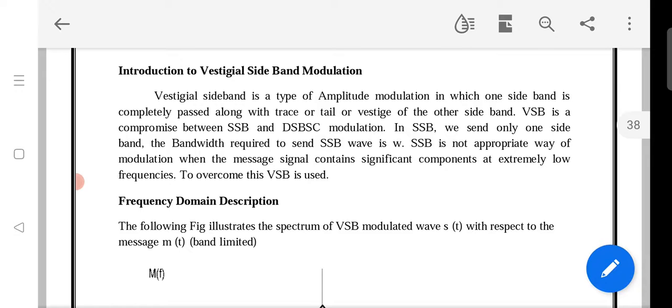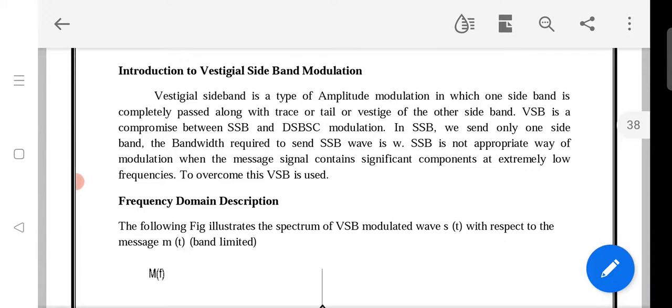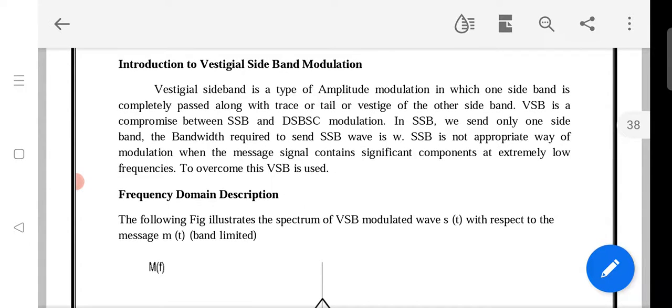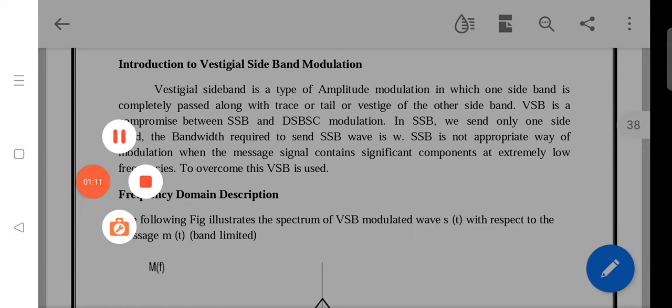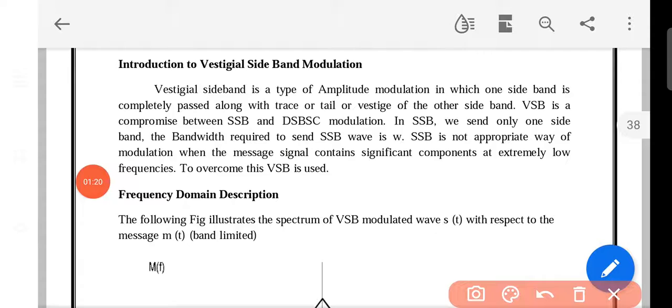For this we achieve the lowest power, a saving compared to AM. But in that also two sidebands are sent in parallel, which have symmetrical information. It means the same information is in both the sidebands. That's why we want to send any one single band, including carrier suppression. That's why SSBSC was incorporated.